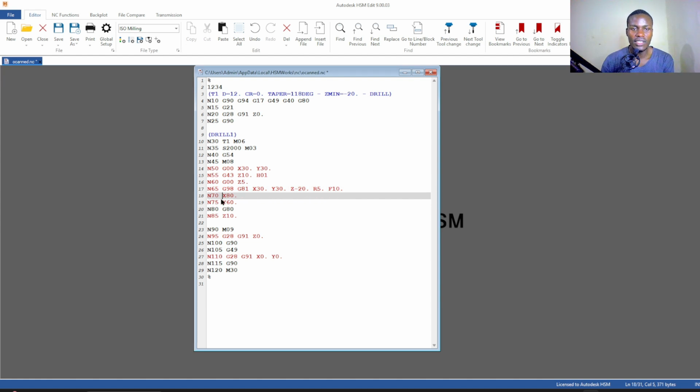And then you see in the next line it will go to X80, and the machine knows that it's still along Y30. In the next line, because it's still X80, it will just go directly upwards to Y60. And then G80 to cancel the above canned cycle. You return to Z plane. M09 turn off coolant. Return to machine origin.